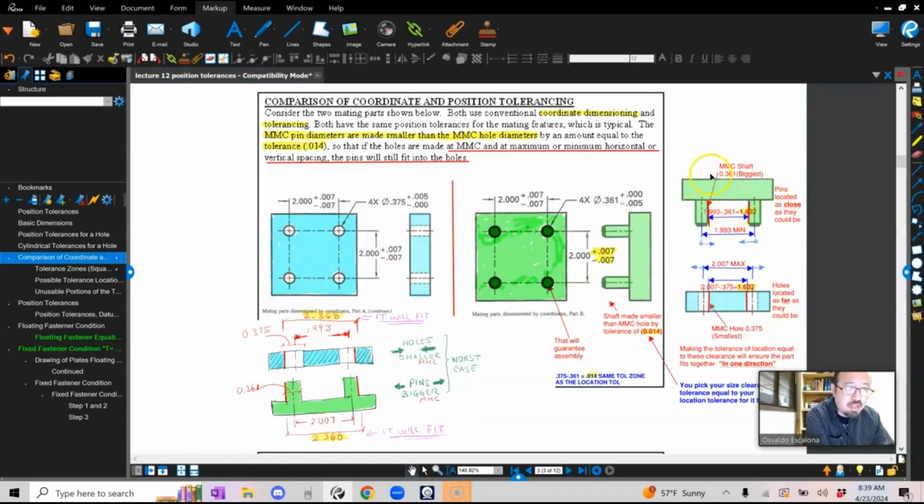So I'm going to grab this plate, this part, and stick it in those holes. In there, you will see that I have a distance of 2 plus 7 minus 7 thousandths, controlling the location. And then I also have the size controlled by this diameter. Now, if I were to look at this hole, that would mean,